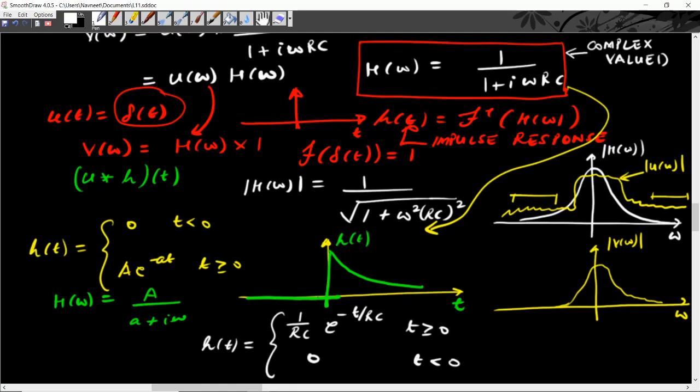So again we have the similar exponentially decaying transfer function for our RC circuit, and note that the width of this transfer function is governed by this time scale tau c, that is equal to the RC time scale that is given by the product of the resistance times the capacitance.